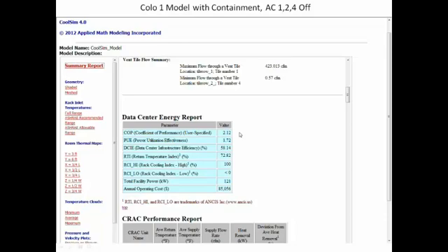I know what the current going into each one of them is, so I can figure out the COP pretty quickly with that data. PUE is 1.72. I'm down below 2. Things are looking good. RTI now, Magnus, is 72.8%. So we're getting there.